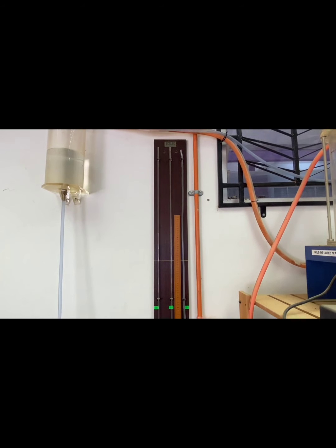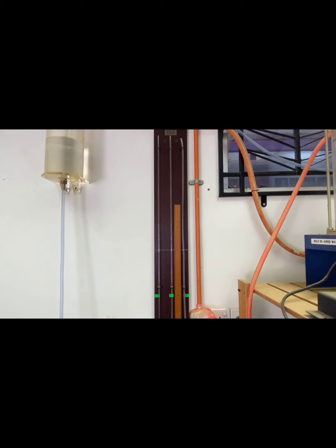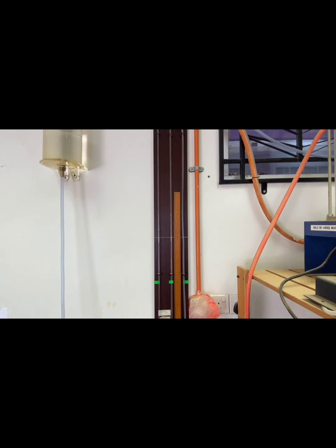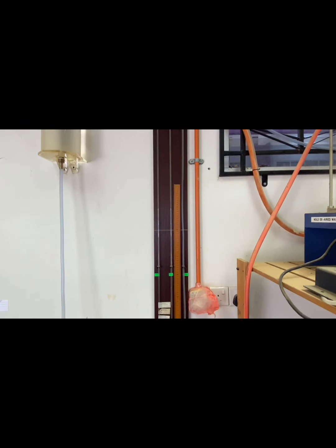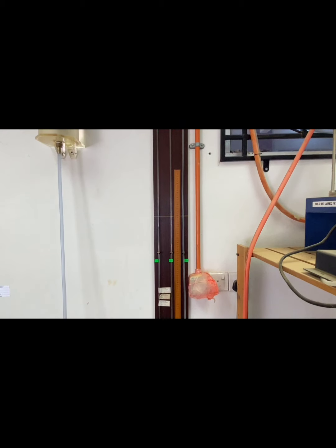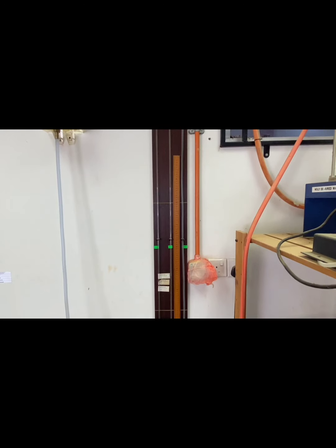The last experiment is the permeability test, which is the falling head test. The objective of the test is to determine the coefficient of permeability of fine-grained soils. The apparatus I used in this experiment are a falling head permeameter, standpipes, reagent cell, stopwatch, thermometer, bucket, and sample extruder.